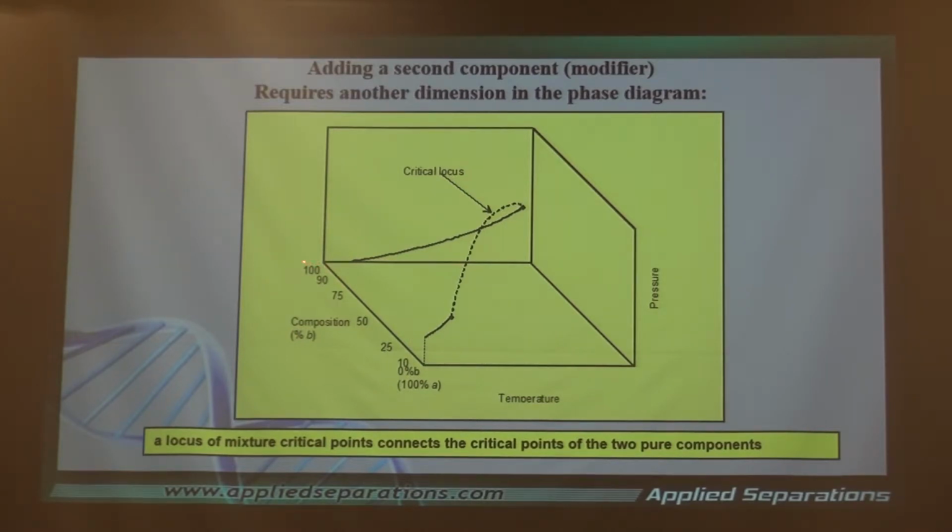Obviously, as you move closer to 100% of this solvent here, let's say in this particular case it's toluene, you will have greater and greater supercritical conditions that mimic the toluene, this point. So as the concentration changes, the supercritical point of the mixture changes. It is this continuum here.